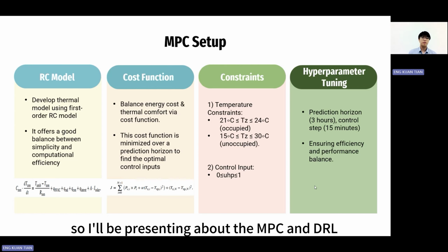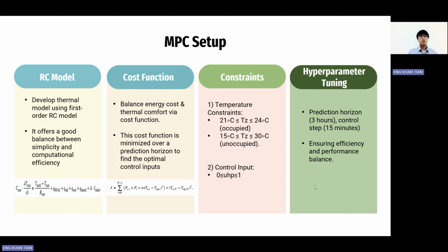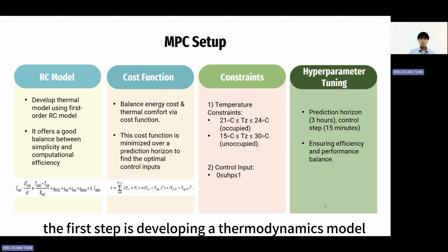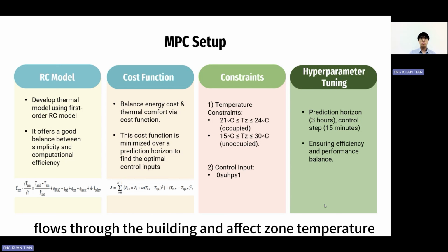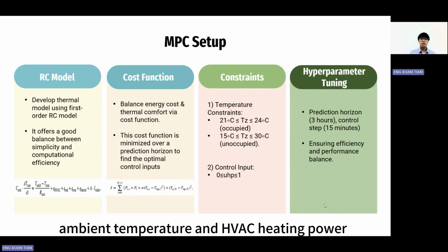I'll be presenting the MPC and DRL implementation. Let's start with the MPC setup. The first step is developing a thermodynamics model of the building using an RC model to simulate how heat flows through the building and affects zone temperature, based on ambient temperature and heating power.